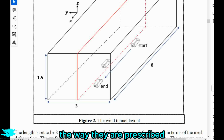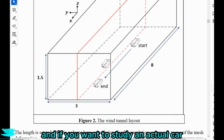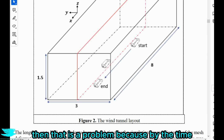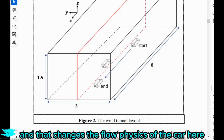The way they've prescribed this boundary condition means that from the very inlet, really, a boundary layer will start to form. And if you want to study an actual car and get accurate results, then that is a problem because by the time the flow reaches the car, the boundary layer can easily be a few centimeters tall, and that changes the flow physics of the car.